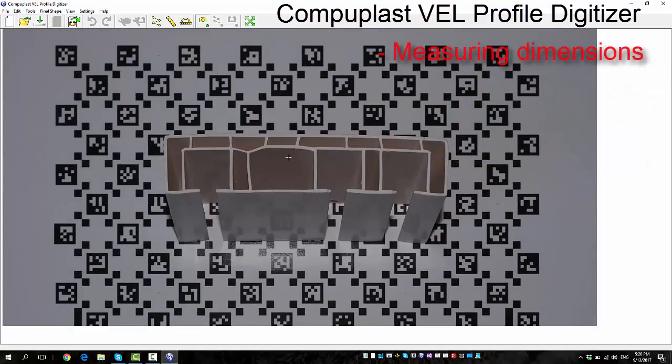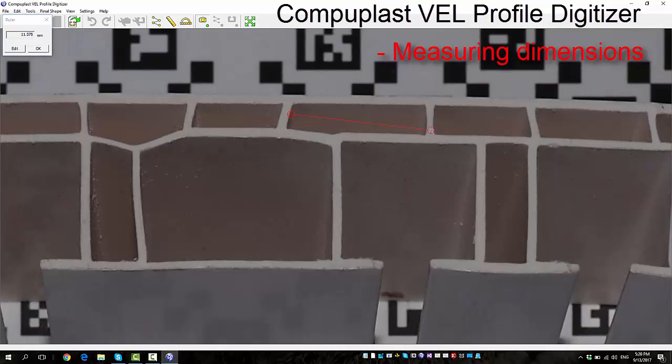The first option is to use a ruler here. We call that ruler, and now you can measure these dimensions. For example, simply like this. You click and drag, and you get the readings. Well, sometimes it happens that you measure by caliper or by any other method and get 70 instead of 69. Still, you can click on it and correct the dimensions, and that will set a local scale which will be applied to all the dimensions in the future. But I don't want to do that now, so I just skip that, and I start the ruler again, and I can measure any dimension.